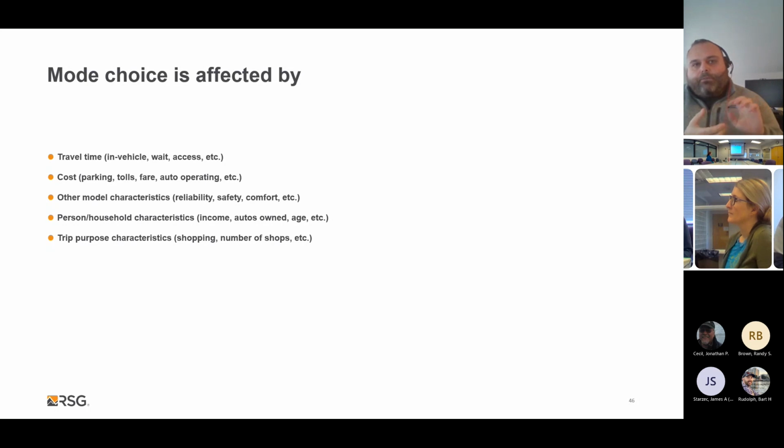And so really what you're looking for is a feedback mechanism. What goes into level of stress? You're not necessarily pulling in your level of stress index. I don't know if you put it on an index or you measure everything individually, but you have multiple things that go into that stress index, like the quality of the bike lane, is it a grade-separated path, what's the speed of travel, what's the percentage of trucks, what's the total volume of vehicles, and stuff like that. And you would put that into a new path choice model that would figure out how to route these trips according to those types of factors. And that's how it's been done nationally.